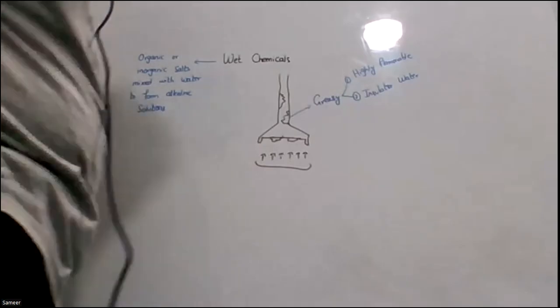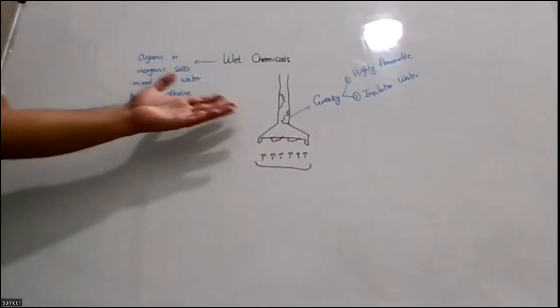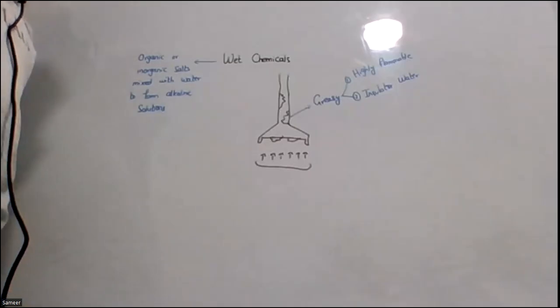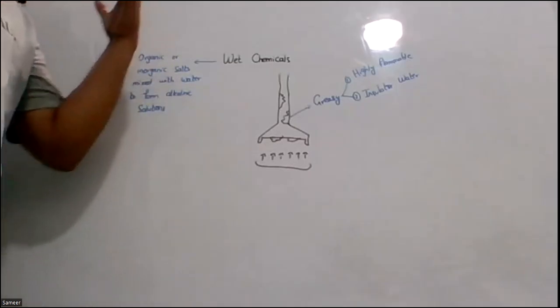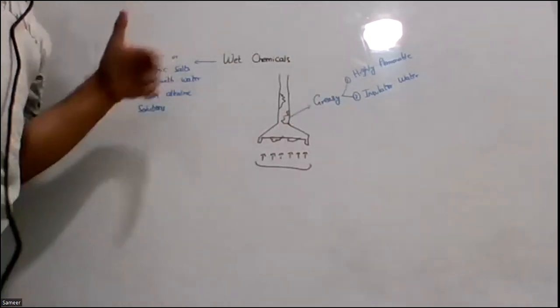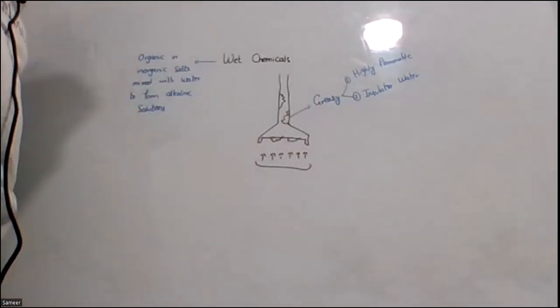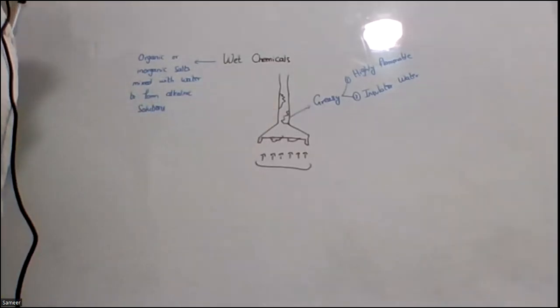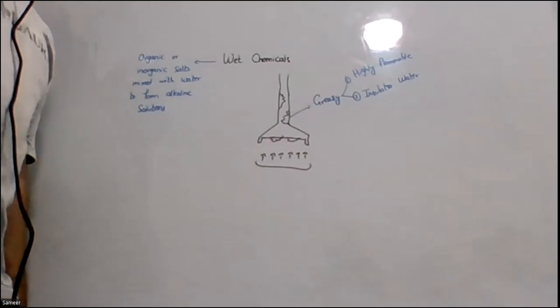So what will happen there? In this case, the flame will propagate, it will continue to burn, and it will burn up to an intensity where it's going to propagate outside the hood, eventually covering up the whole kitchen. And in worst case scenarios, it may also cover all the occupancy also. So usually what we want is to get rid of this greasy formation. So there we come and we tend to introduce our wet chemicals.